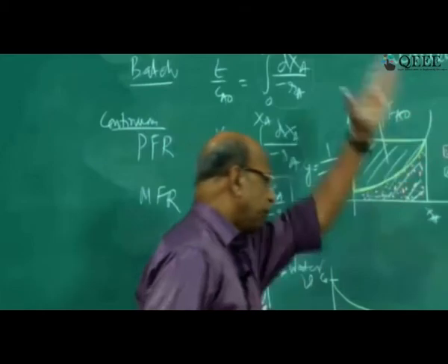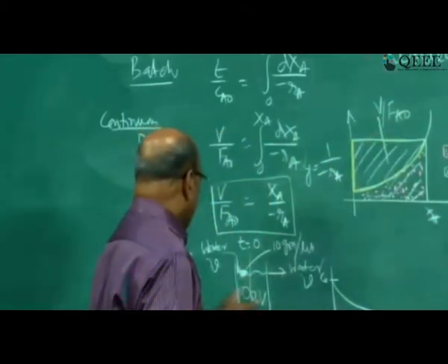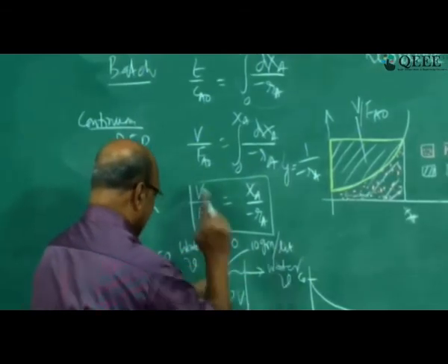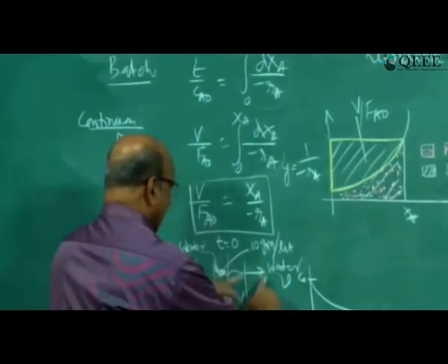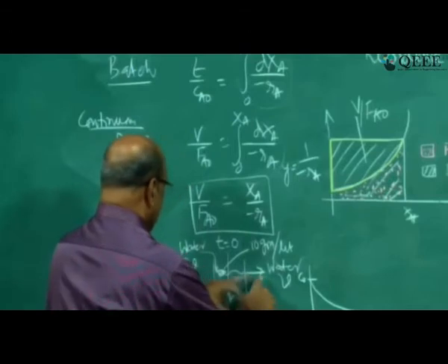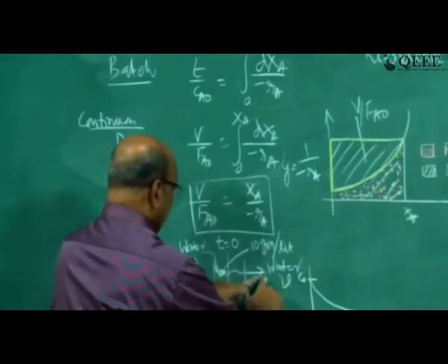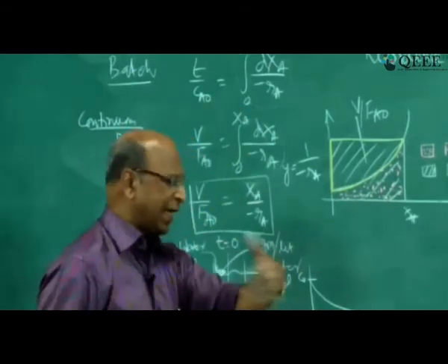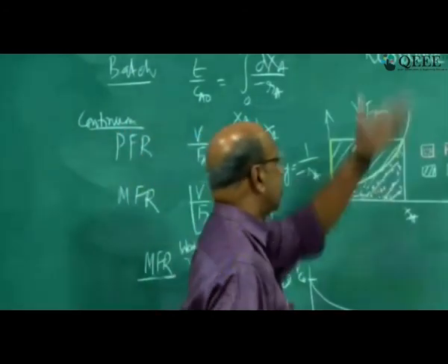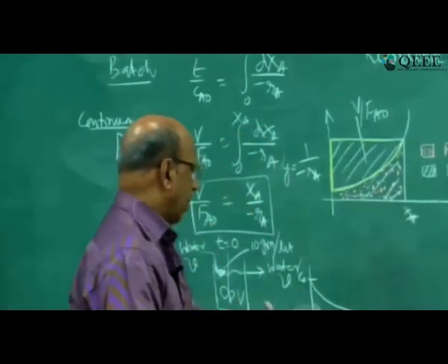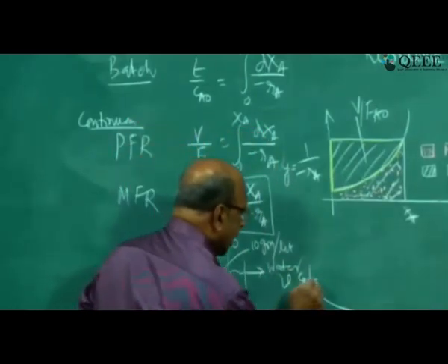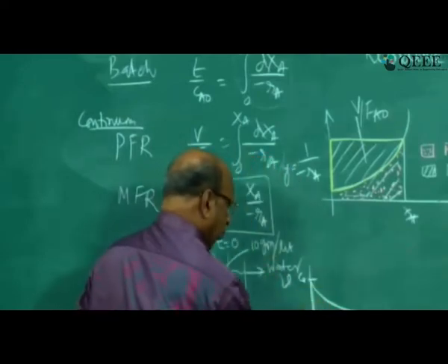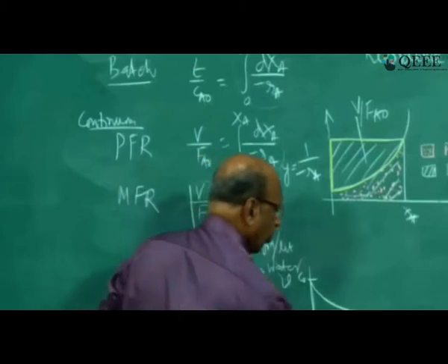And then it goes to infinite time to remove all the color, because you see that we added only one drop. Water is continuously entering. Water is water, there is no color at all. And here you have colored water. Finally, for this colored water to become pure water, the original water, it takes almost infinite time. I think we can write a material balance and then do it, and that comes in residence time distribution. But my point here is, we have the water molecules coming, ink molecules coming from time t equal to 0 to infinity.